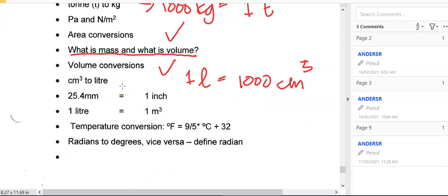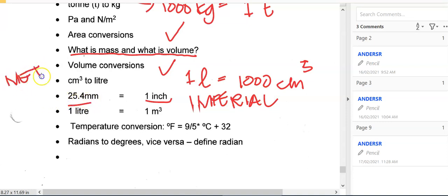Okay, and you might or might not know, many years ago, before you were born, when I was a kid your age, we called this the imperial system of measurement, and we call this the metric system of measurement, which is actually French. So to convert from imperial, 1 inch to millimeters, you multiply by 25.4. 2 inches you multiply by 25.4. Okay, and that is that conversion there. You must know it. Often when you pick up a plan in site surveying that's been drawn, let's say 30 years ago, it's in feet and inches in imperial, you need to convert it. That is the basic conversion.